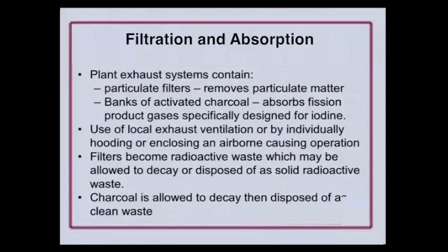And these are huge banks. I'm talking about ventilation units that are the size of this room. And probably 3/4 of this room would be a charcoal bank, or a series of charcoal banks, to exhaust a place like, say, the turbine building. You'd have 2 or 3 rooms like this. What it does is it captures the radioiodine and it holds it.